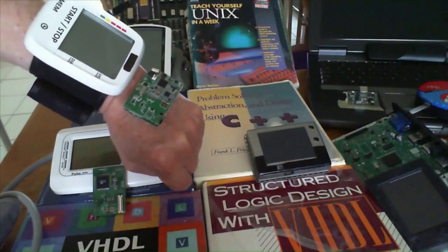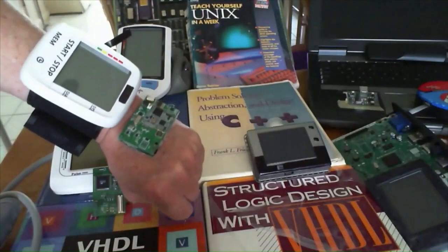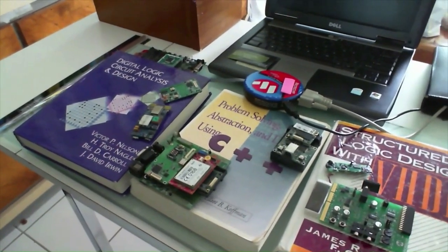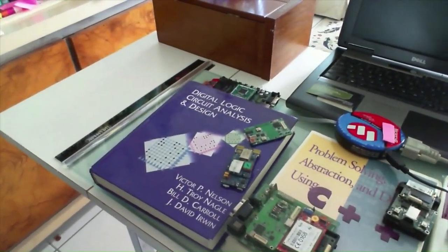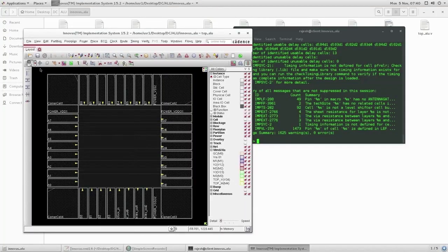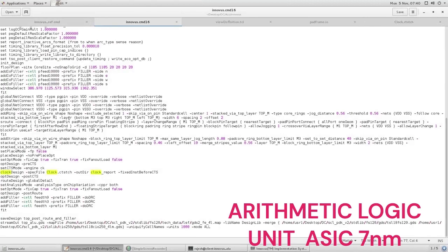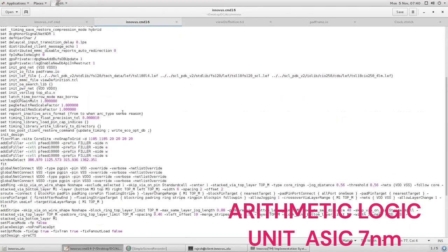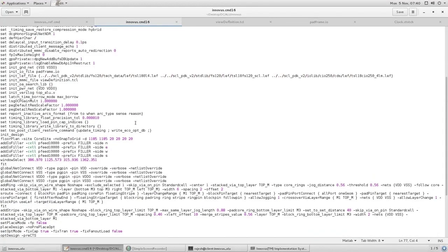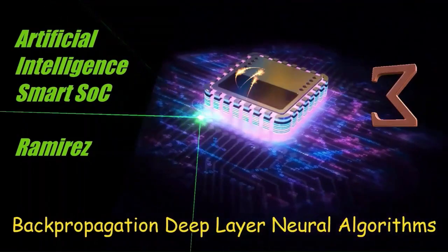A set of timing critical nets can be routed in the second iteration after analysis has verified that these nets meet the timing objectives. The remaining nets can be routed in the third iteration without changing the wires for the clock and timing critical nets.